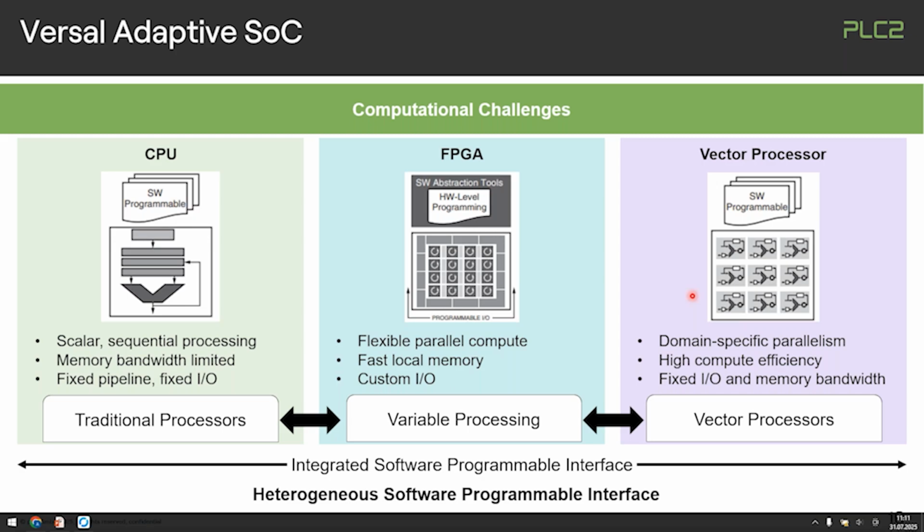These guys cannot do the highly sophisticated instruction set stuff that the CPUs can do, but in the end, they would still be available in a much higher density and a much higher parallelism. So we're talking about thousands of cores compared to a few tens at the CPU level. And now the programmable logic is just the workhorse of most distinctly implementing anything in there, because you can put CPUs in the programmable logic, like soft core processors, and you can have vector processing designs in their parallelism of implementations that would simply do a very distinct instruction in this case.